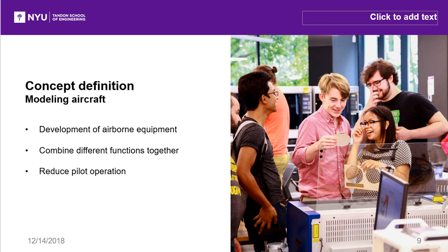Appropriate aircraft motion models should be used at different stages of research and development of the flight management system. The performance of aircraft considered in the FMS study is mainly a series of tables and aerodynamic characteristics that characterize the aerodynamic characteristics of the aircraft. Among them, the characteristics of lift and drag are the most important.